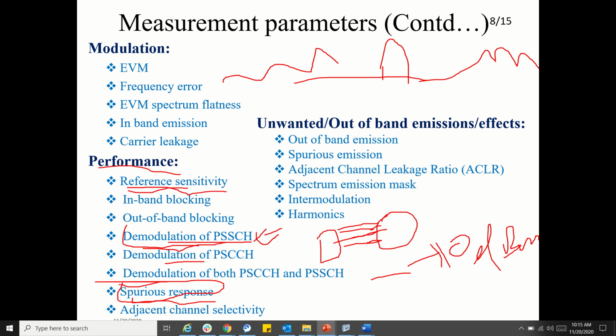Because it is an RF device, several components are embedded in the system, and they emit different kinds of frequencies that add together and create intermodulation products. Obviously, RF components have harmonics, and some of those harmonics add together and create further intermodulation products.